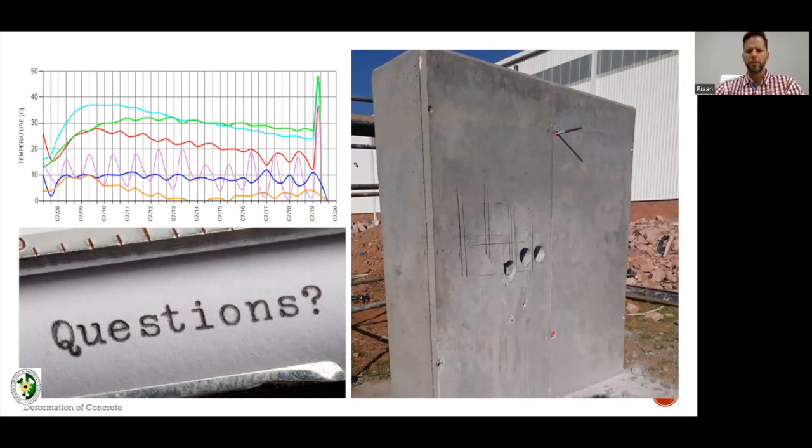Interesting thing about efflorescence: a part of the whitish substance that leaches to the surface, initially it's calcium hydroxide that leaches to the surface. Now, calcium hydroxide is water soluble, as you remember. And if there's moisture in your concrete, the fly ash then reacts with it to form more CSH. If water moves through a wall or through a slab, it brings this water soluble calcium hydroxide liquid to the surface, where the moisture then evaporates off the surface and leaves the calcium hydroxide white crystals on the surface.